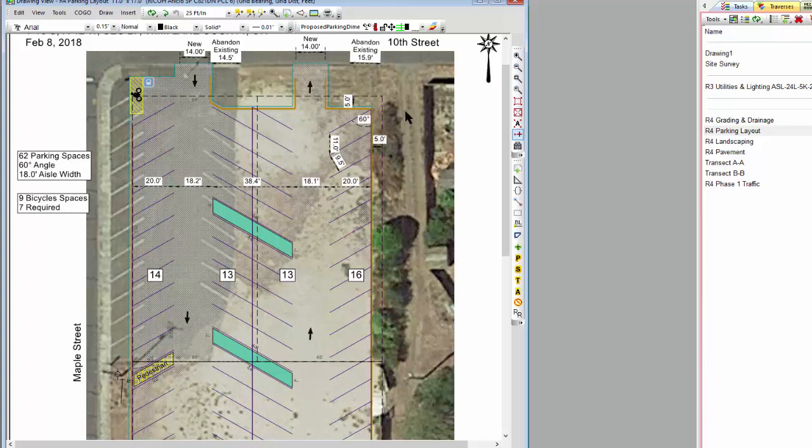Alleyway, this is interesting. We have an existing driveway cut right here. Originally I thought, well, it'll be real easy. We'll just use that, or we'll kick out of the alley here. But the city said, if you want to access the alley, we're going to make you improve the alley. That means subgrade, rock, and asphalt. No way we're going to do that. So we went ahead and put in a new driveway cut here, and I think we did just fine like that.